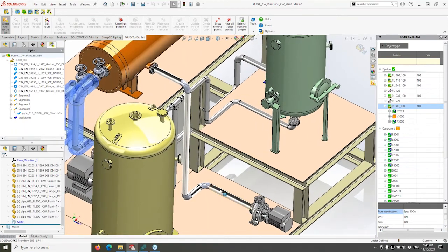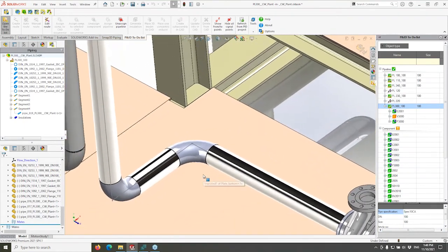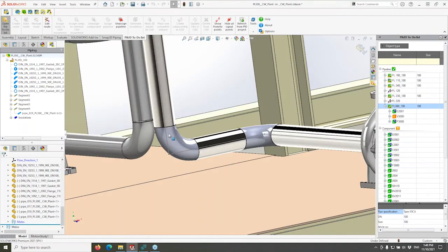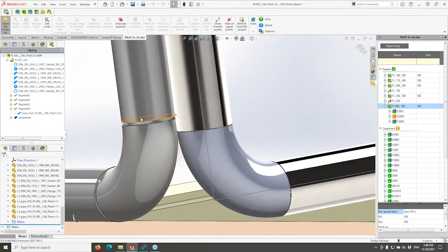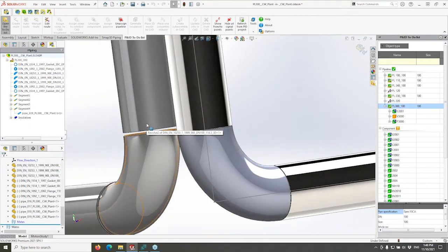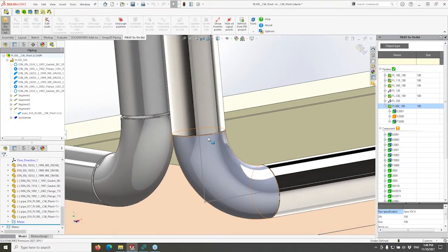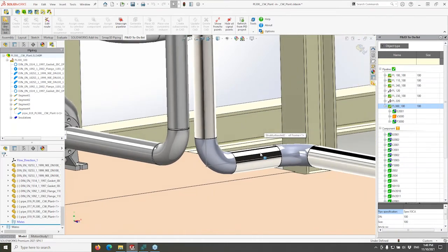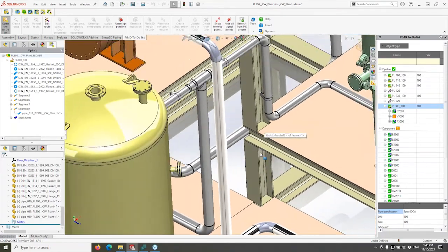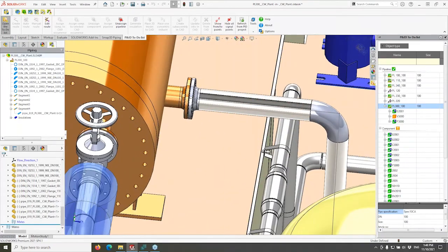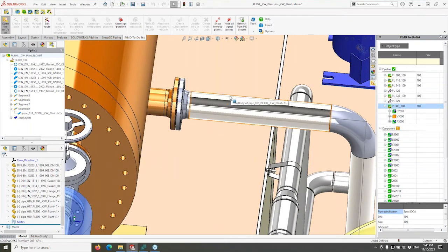correct fittings so that it knows whether or not you want to use welding gaps or not. Notice in the background here, I have another pipeline with weld gaps in there. This is just an option to turn on in your pipe spec because some companies want to design with pipe specs to get more accurate cut lengths of each piece of pipe. Other companies say, we leave that up to the shop, let them figure out their weld gaps. We use different shops all the time, and we don't want to commit to a specific weld gap and then it costs us more money or we're not able to do it.